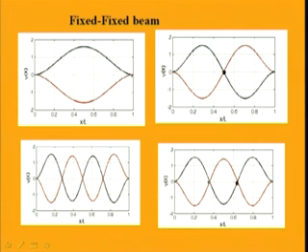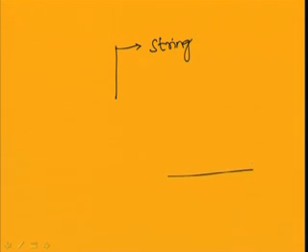In case of the third mode there are 2 nodes, and in this case you have 3 nodes present. So, the systems represented by wave equations, we have studied about 3 systems. In the first system we have studied about the string, the taut string, so in this case the string is in tension, the vibration of the string in tension, and the longitudinal vibration of beam,